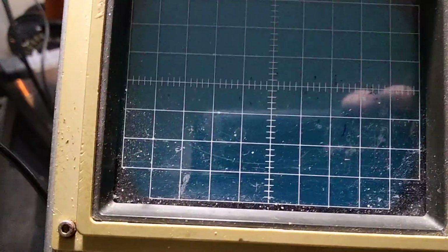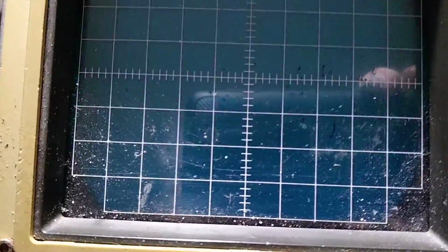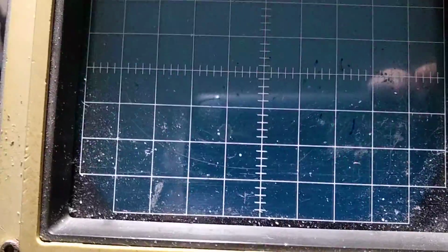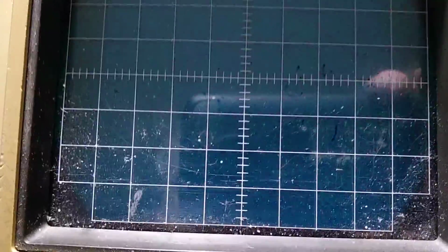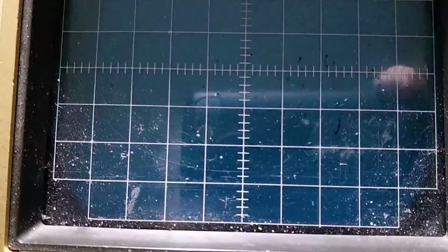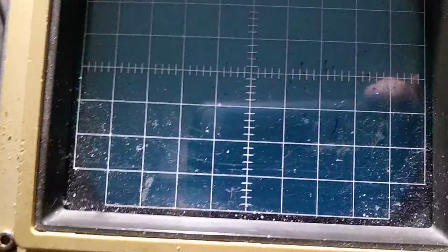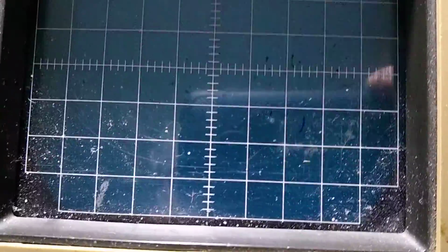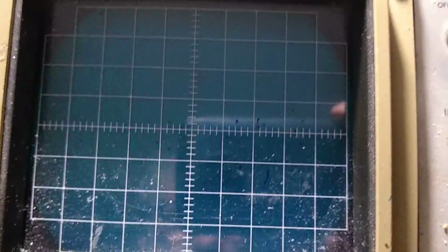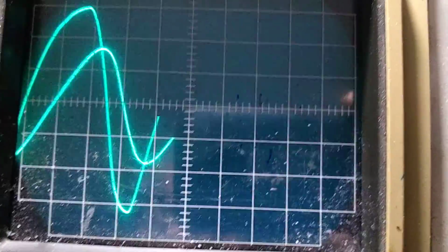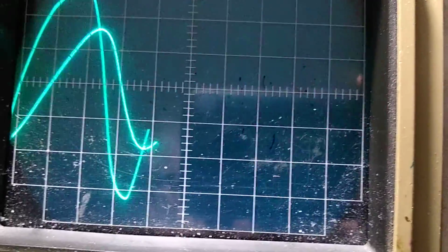And overall, one cycle is 21.5 spaces, minor square divisions. The small spaces within the big squares, the bigger squares. And for peak to peak, I'm saying 18, might be 17 actually. Let's just say 18 spaces peak to peak.